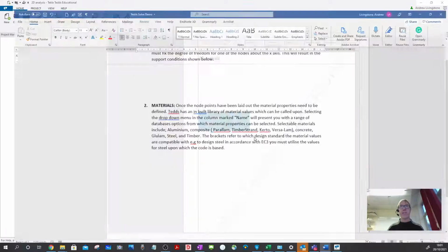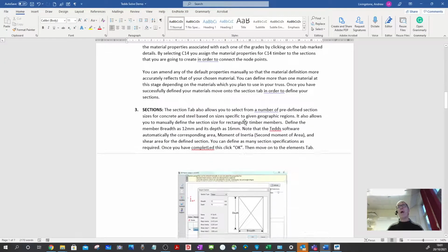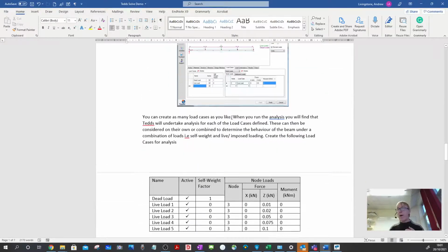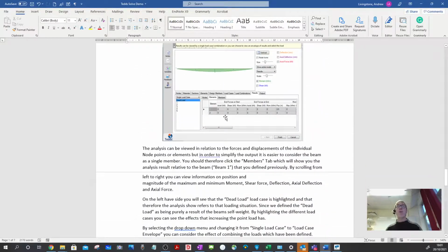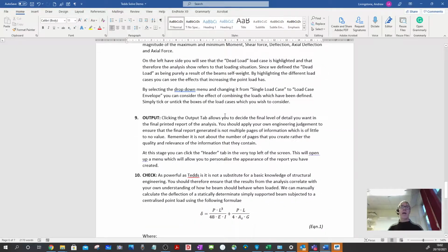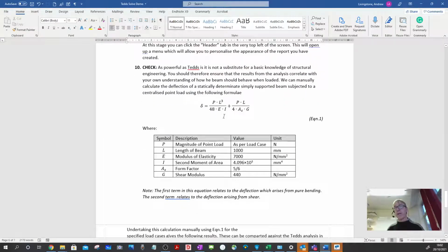what we have in the Word document for this example is an explanation that it's all very well having the nice software, but you need to make sure that the data you put in is giving you out the answers that you would expect. Quite often what we would do is double check an element of the building where we can easily check just the one part of it. So this is a nice example here. There's the equation to calculate the deflection at the middle of that beam, and there's some data there. And I've actually typed this up in Excel for us.